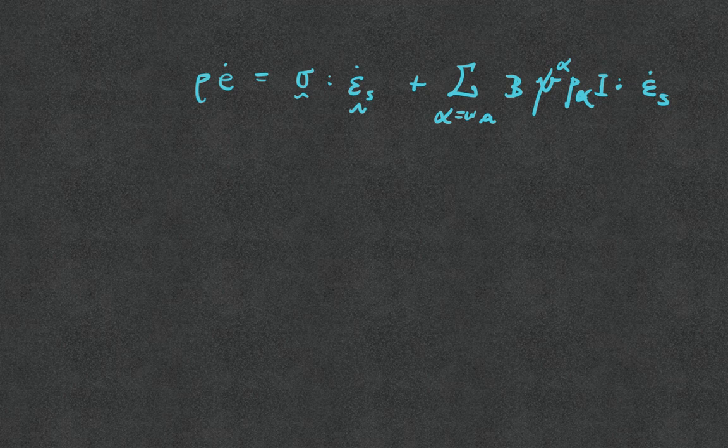And the degree of saturation is also not necessarily equal to 1 because you need to accommodate the fact that the void space can be occupied by either the water or the air. And hence, we also have two different kinds of pressure: the pressure of alpha that represents the pressure of water and the pressure of gas.